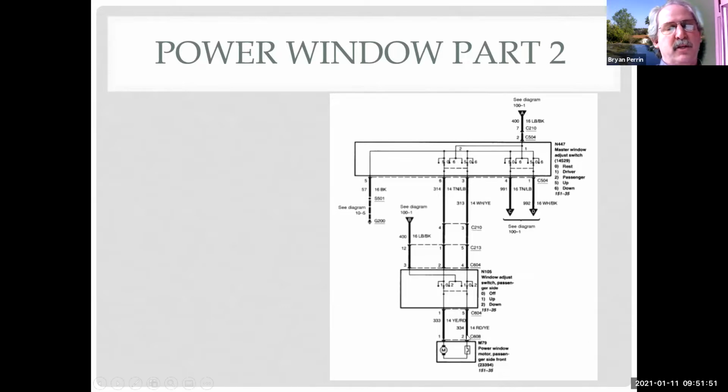So the easiest thing to do a lot of times is get to here and test it, or if I'm going to pop a switch out, check the outlet side of the switch. When I switch, do I get power? Go the other way, I should get ground. The other one should be the opposite. Usually what we find is the contacts have gone bad in either the power or the ground side where we don't get a good switch.